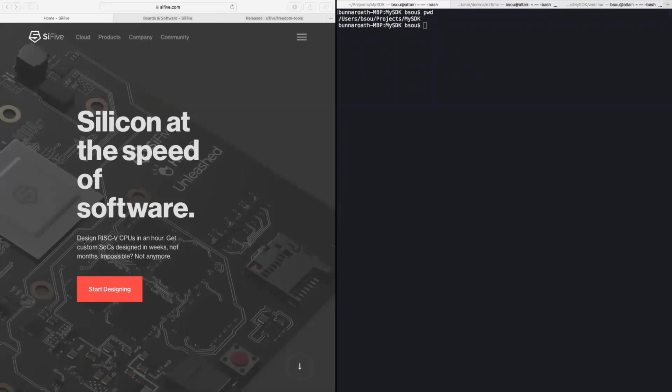Hello, and welcome to this demo part of the webinar. I am Bunaroth Su. I am a software manager and lead for the Embedded Runtime Software Group. I am going to walk you through how to build and run a couple of embedded RISC-V software examples using SiFive Freedom E SDK from the command line. I am going to do this on my Mac running High Sierra OS, but it also works on Sierra OS. You can also use a Linux machine with Ubuntu 16.04 or 18.04. You can also use it on a Windows machine running Windows 10, but you will need to install the Windows Subsystem for Linux in order to run the command line.